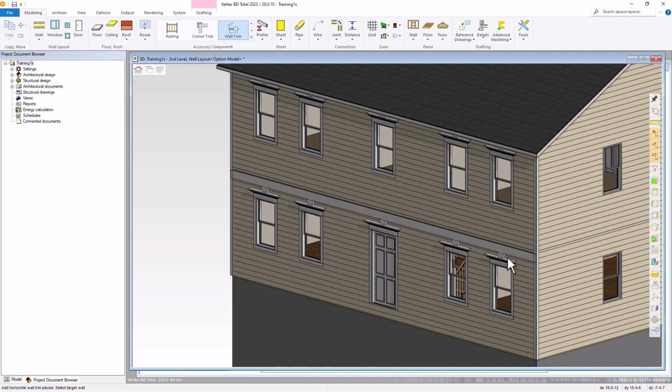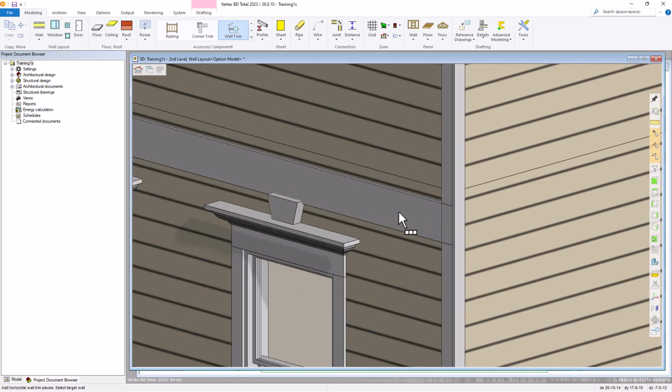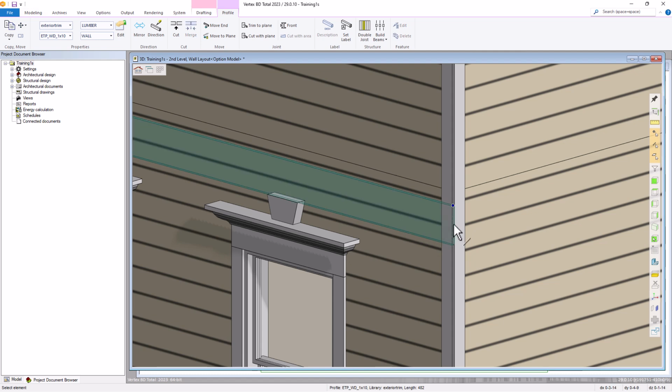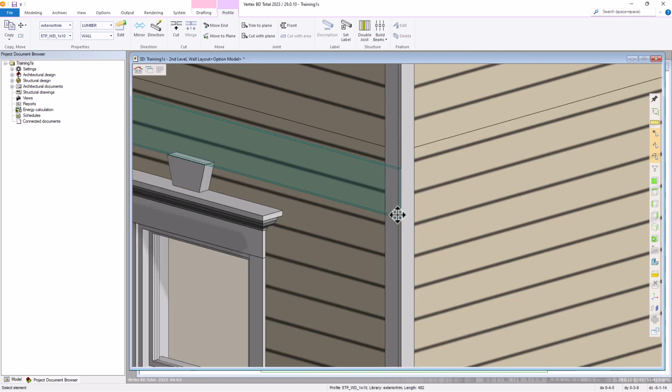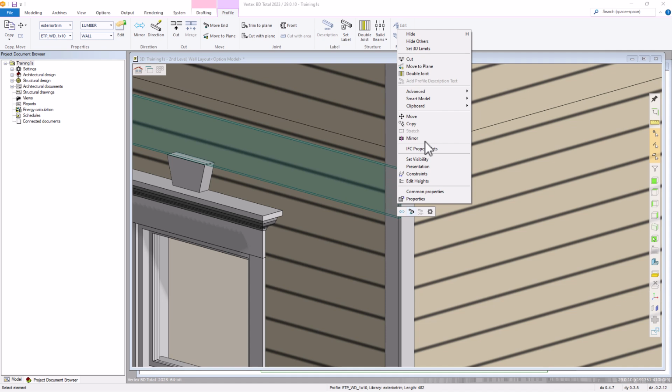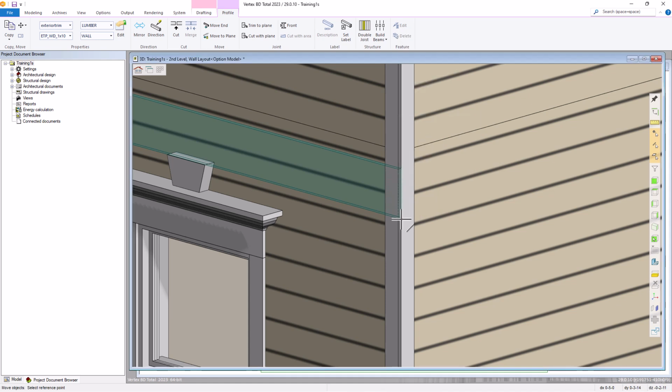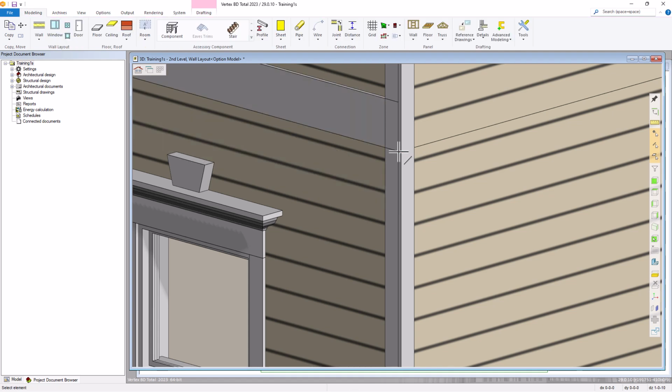And if it doesn't locate it exactly where you want, you can go ahead and move it. So I'll hit OK or escape. I'm going to take this trim, select move, set this corner as my reference point. Right there, lock it in the O for the Z axis, and put it in line with intersection. So I hit S to find the intersection.